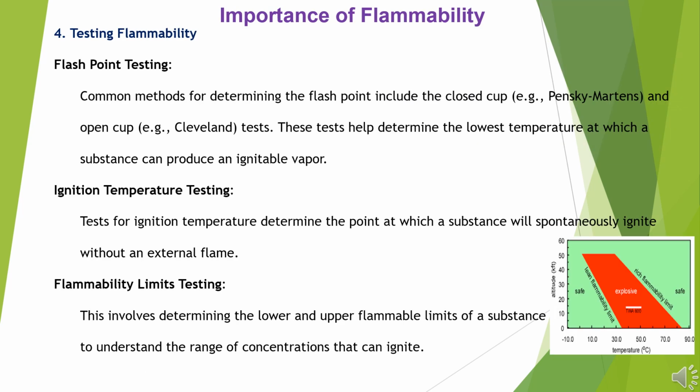4. Testing flammability. Flashpoint testing. Common methods for determining the flash point include the closed cup, e.g. Pensky-Martens, and open cup, e.g. Cleveland, tests. These tests help determine the lowest temperature at which a substance can produce an ignitable vapor.